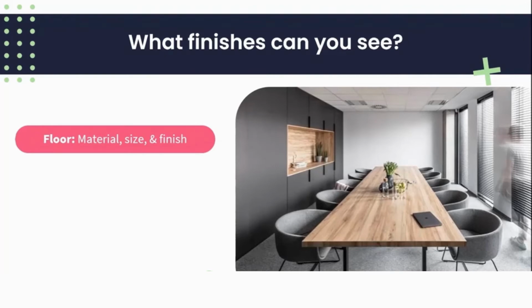So what you do here is you'd measure out the size of the space and give that size as the size of the material required. And that would then also lead into the quantity needed. And then for the finish, we need to explain what carpet it is. It's a rough textured carpet, it looks to me. It's a gray colored carpet and it might have some black flecks in it. Obviously, we'd need to see the sample close up to provide this detail. And then I would also go to the supplier and ask the supplier for an exact specification for this carpet and use this on my finishing schedule.